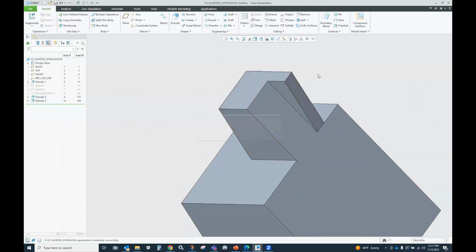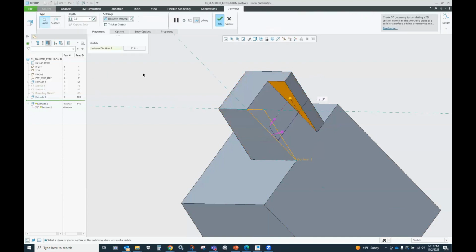So my depth option right off the bat is pretty lazy, if you ask me, right? I really should use a different option from this list. Does anybody know what the best option is in this case? Through all. Through all. Okay.